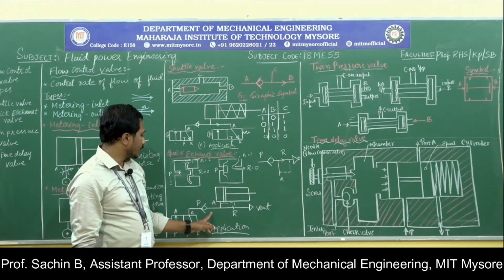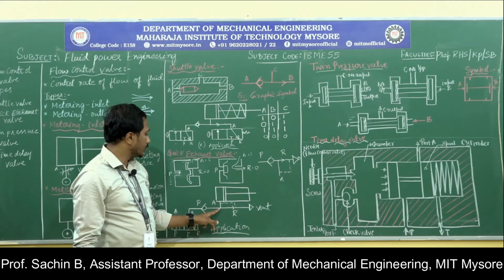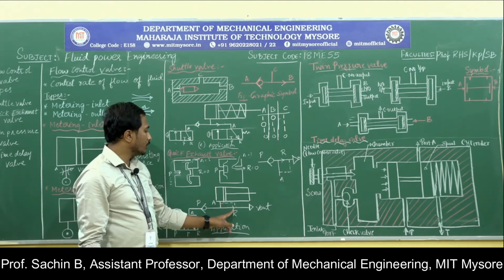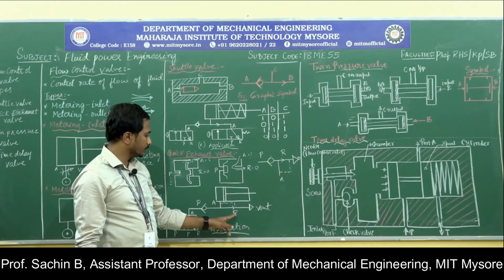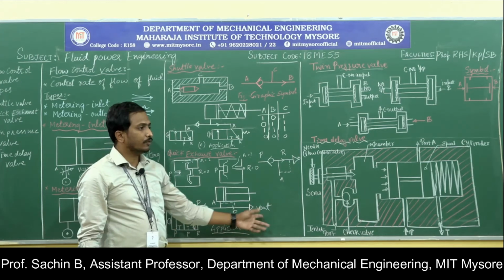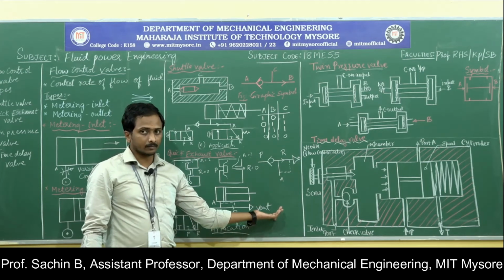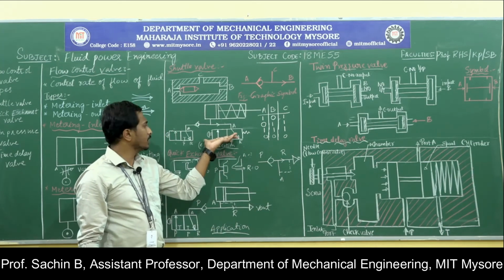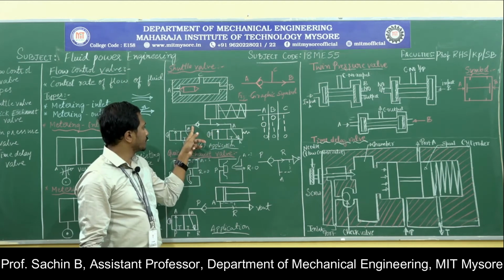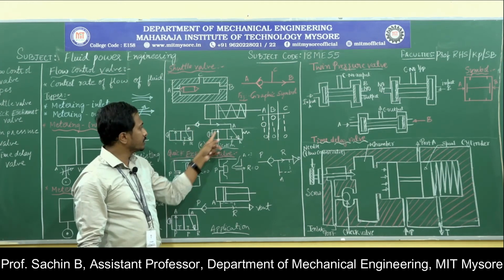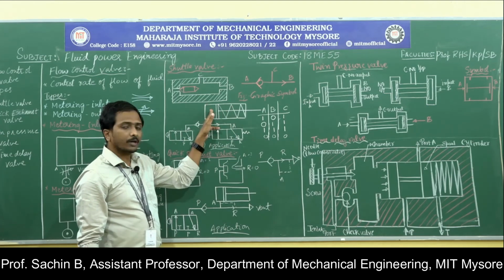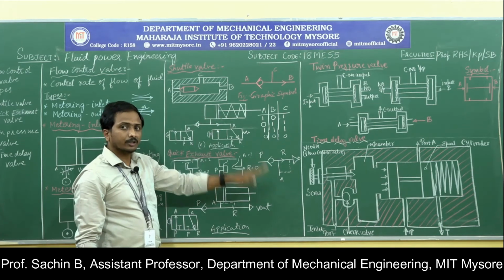Again while coming back here, the fluid will not come back to this valve itself, to the reservoir. There is one more direction we have provided here, that is the reservoir symbol, which will send the fluid to the vent or directly to the atmosphere. In this case we are using 2 valves here. You can clearly observe, once the compressed air enters, that is also released, and while retracting back, whatever amount of fluid is present inside the cylinder is also released.